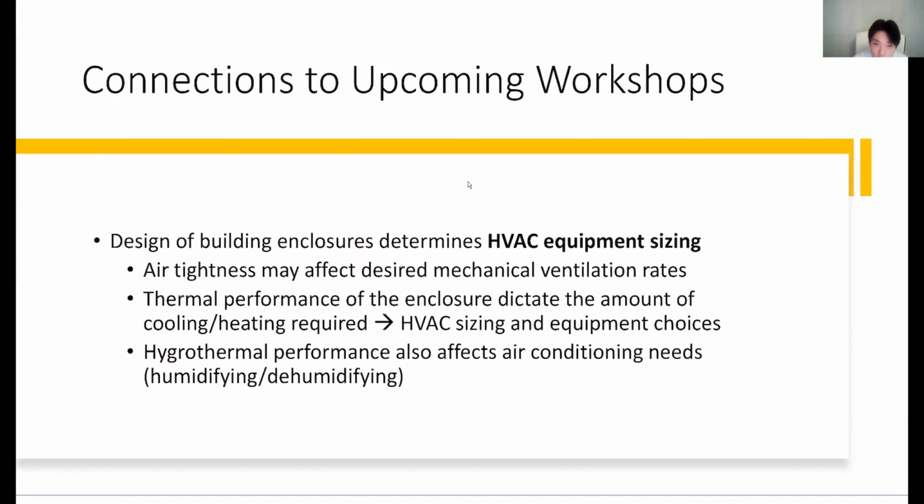So the design of building enclosures, as we talked about today, really determines how we size our HVAC equipment, basically our cooling, central heating, or conditioning units, because if we have a very thermally capable enclosure, we don't need much heating or cooling, right? So that determines the HVAC equipment sizing.